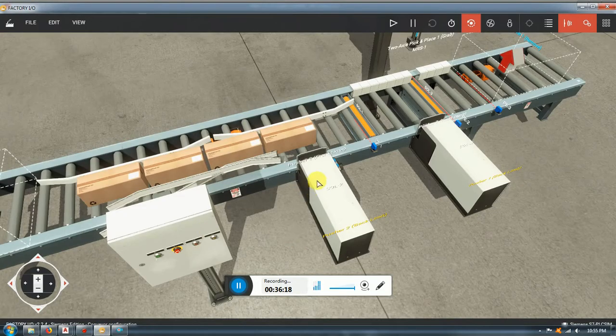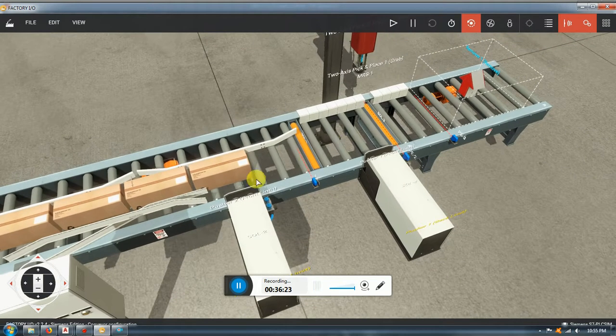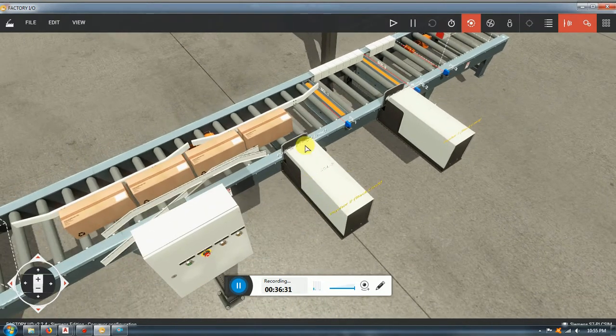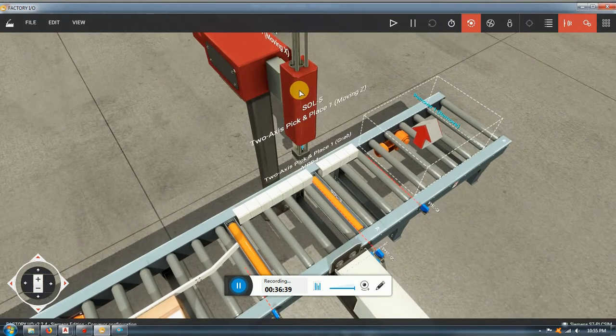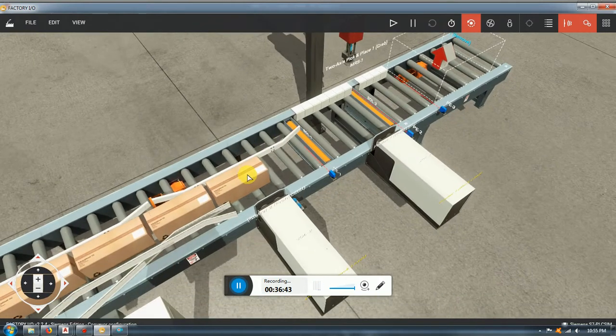you also want a specific regulator for some of the cylinders. Why do we want that? To control the force that they're pushing against the items. So for example, I want to be sure that that cylinder is not going to be pushing too much pressure, or we're going to damage these boxes. The same thing for that one, and the same thing for this one. This one especially, the stamper has to stamp with a specific force that is not gonna damage the product. If they damage the product, we have issues, okay?